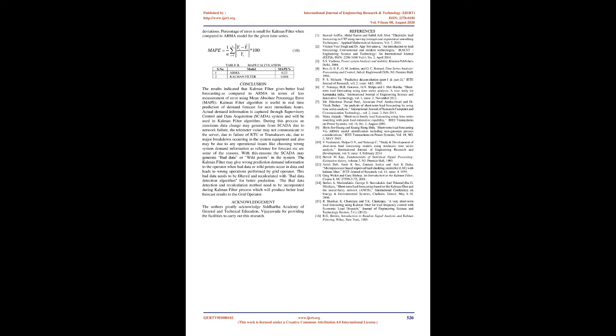Conclusion. The results indicated that the Kalman filter gives better load forecasting as compared to ARMA in terms of less measurement error using mean absolute percentage error, MAPE. The Kalman filter algorithm is useful in real-time prediction of demand forecast for the next immediate hours.